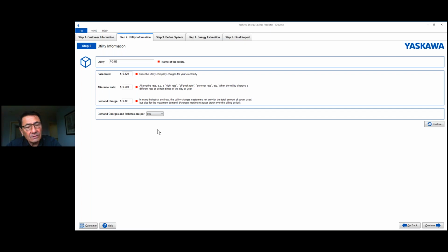So this is a nomenclature issue. But for every, let's say, 1,000 kVA that the power company gives you, if you effectively use 900 kilowatts or more in the actual movement of the water, as opposed to wasting it with harmonic distortion or too many transformer loads or whatnot, then your power factor will be 0.9 or above, and the power company would be pretty happy.